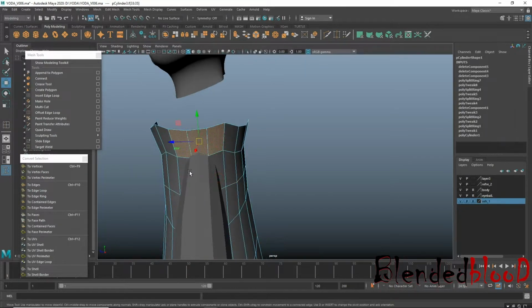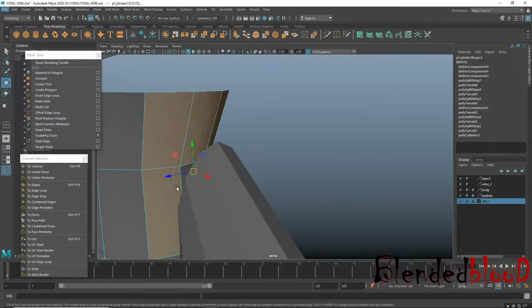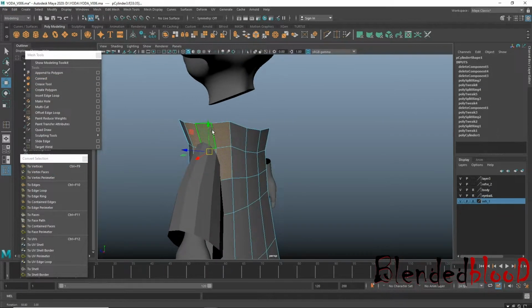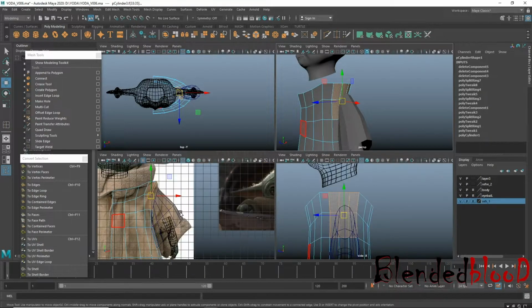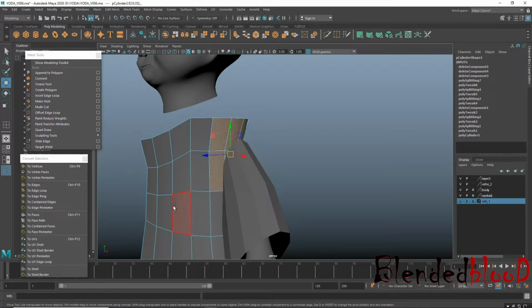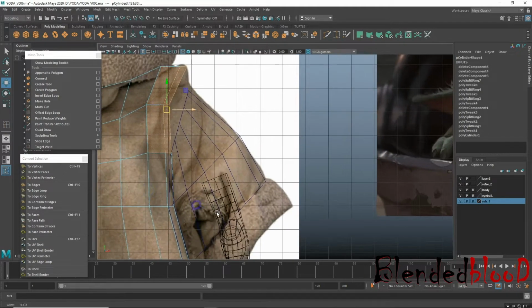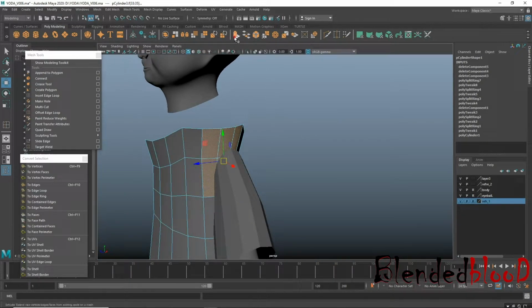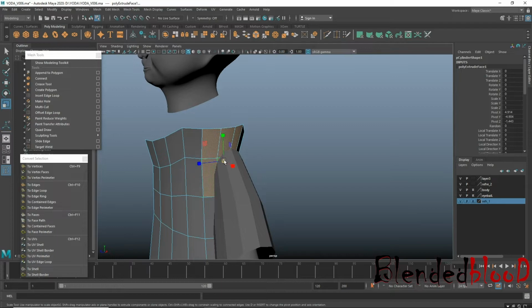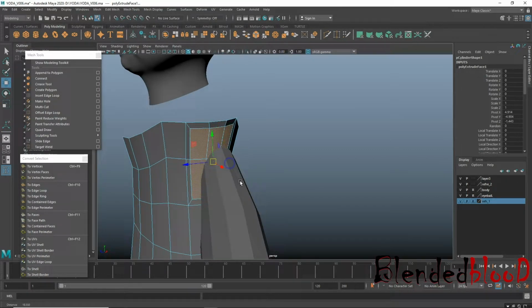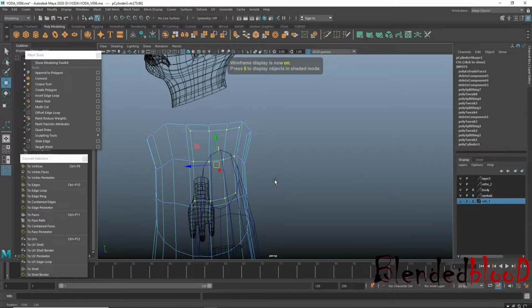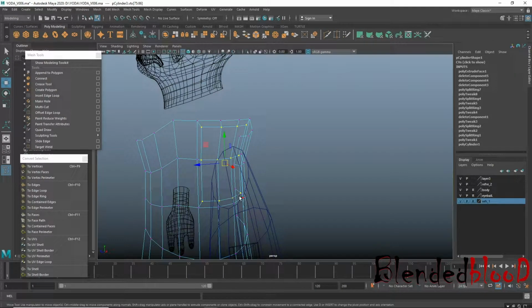if you select these 6, and just look for the vertex, but yeah, it's just a second. Click on extrude, press R and scale a bit. Now click on selection, convert it to vertex, press 4. Now count the outer vertex. 4 5 6 7 8 9 10.